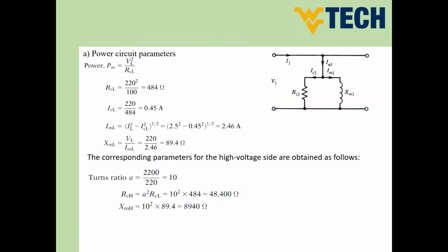So starting firstly, guys, with the no load test. This is the equivalent circuit of the no load test. Now, guys, I have V, I have I, and I have power as well. I'd like to start with the easiest part. You know that power, guys, is consumed all of the time on resistors. So now you have the resistor. In general, power could be I square R, or it could be V square divided by R. This is generally the power across a resistor. But this is only if you have a resistor like that, and you know the current flow and the voltage around this resistor.